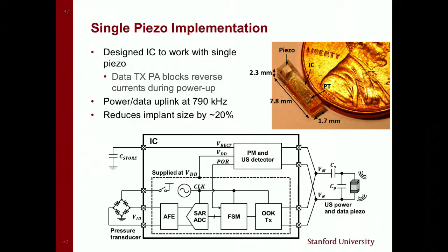One of the last things we did on the systems is we actually used the same transducer for both transmit and receive. If you've designed duplex systems, you know that there's a lot of concerns here on how the transmitter and receiver will interfere with each other. So you have to build the electronics on the chip to make sure that interference is mitigated and we have reliable operation. But doing this will shrink the size of the package because now you have only one transducer doing the whole thing on a TDD system.